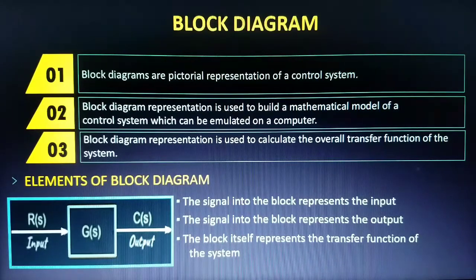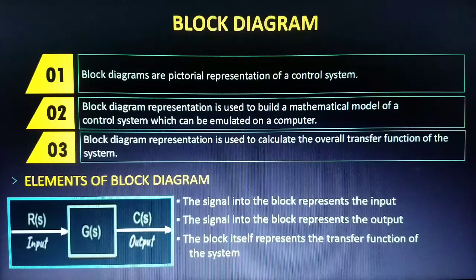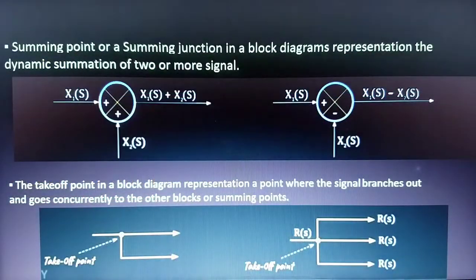They consist of multiple subsystems, interconnections of many blocks, which are connected with branches and arrows. So to analyze those complex representations of a block diagram, we need to discuss some more elements of block diagram, like the summing point and the takeoff point. So now we will move on to the discussion of summing point and takeoff point. First is the summing point.